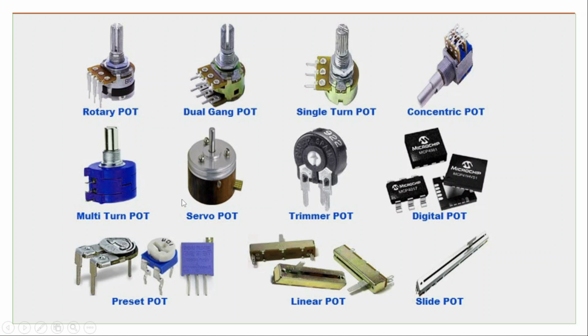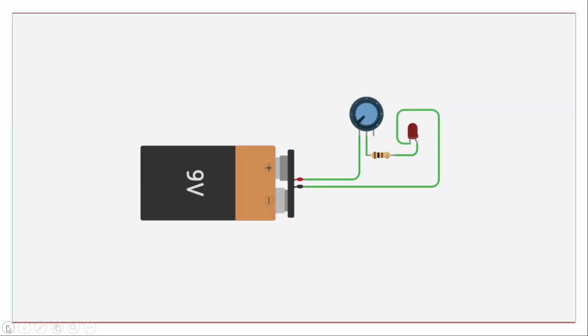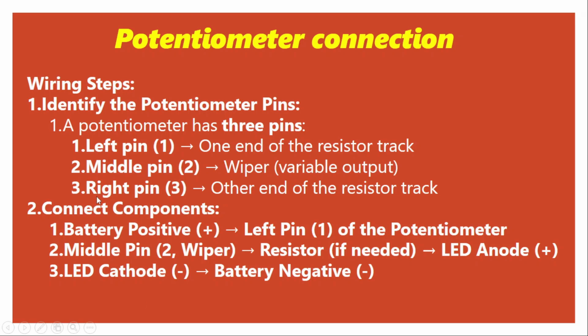While a resistor limits to a certain number, you can adjust the potentiometer for ranges of numbers. Every potentiometer has 3 pins. The middle pin is called a wiper. That's the pin that controls the adjustment, or the pin where you can read the value of the potentiometer.